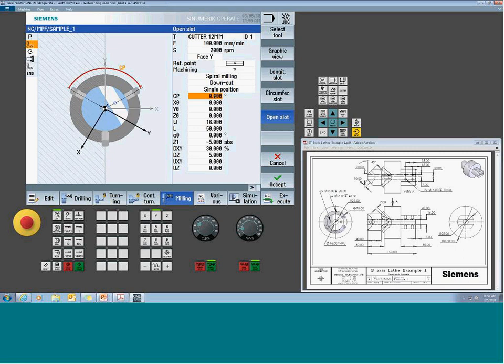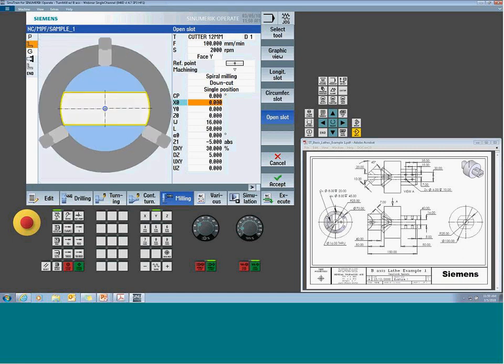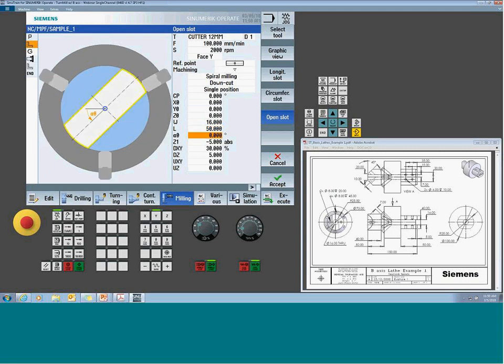And then think about that later, my other features, right? I've got a couple flats I have to put on this part, and some drill holes, and they're 90 degrees off the slot. So you just have to pay attention to that. But that's how I can clock the feature around. This is just your center, the top of the part, and the length and width of my slot. So 16 mil wide, 50 mil long, something just a little greater than that, and orientation if I need to.